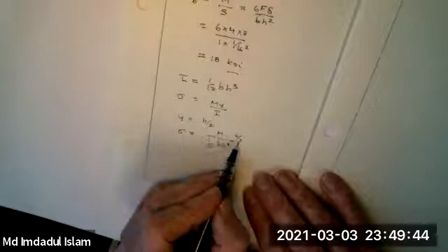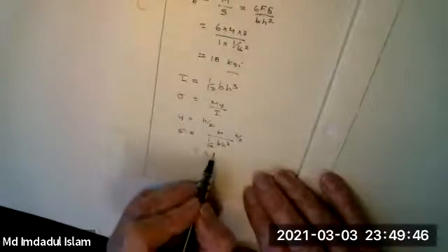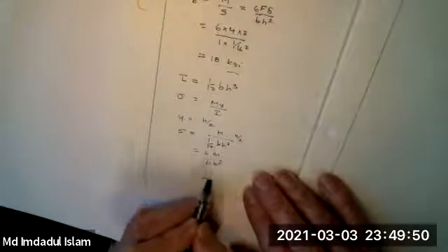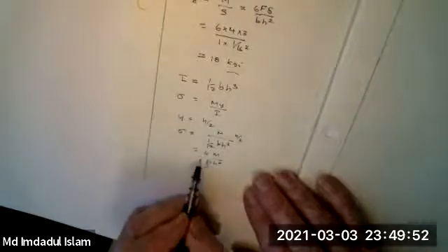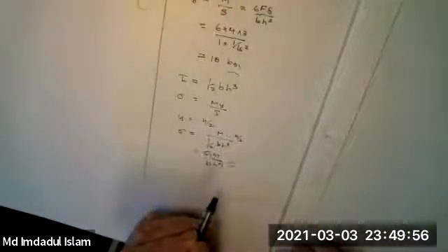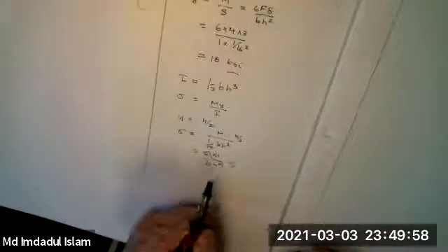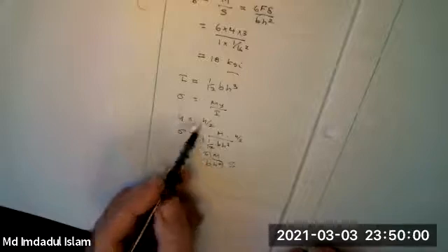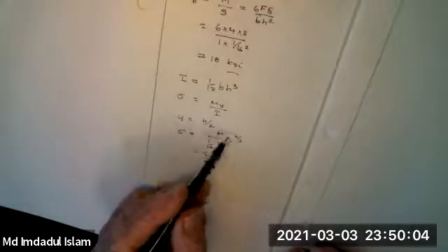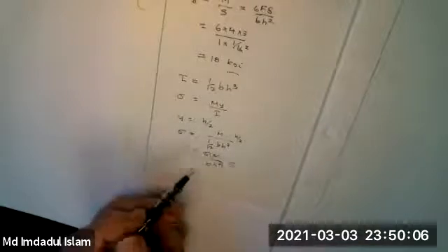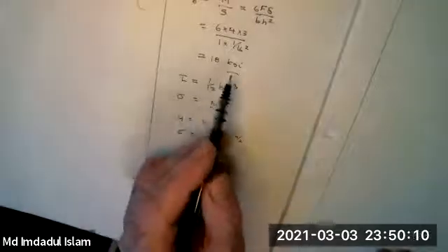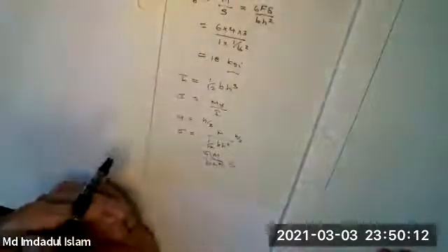the 12th goes up top, divide by 2, you get 6. One of the H cancels, you get BH squared. So this thing here is called S, the section modulus, okay, in bending. It's just I divided by half of the height. Okay? And anytime you're doing stresses in bending, the bending stress is always M over S. Okay.